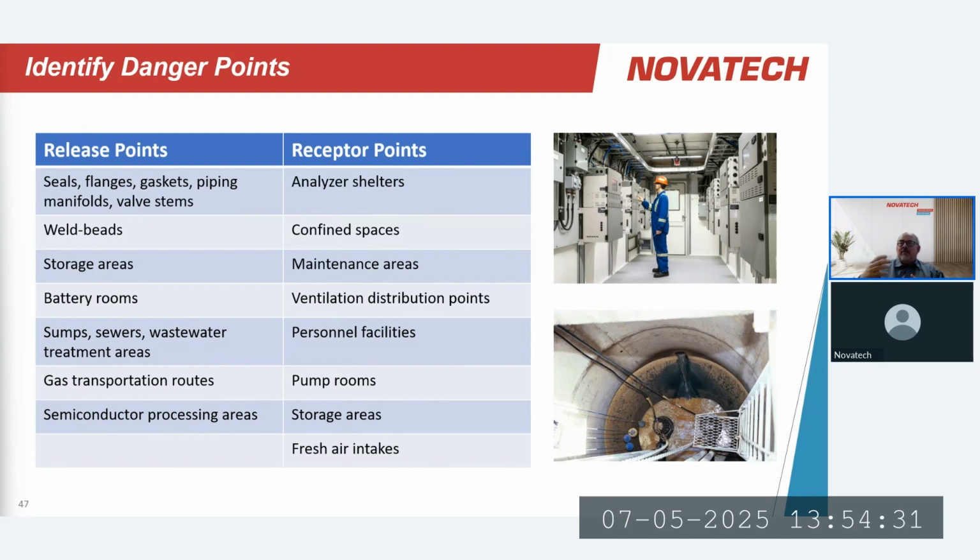We may look at, from a different perspective, rather than looking at the points of release, we may look at the points where we are concerned about the gases being present, whether it's where personnel may exist, so something like an analyzer shelter, a maintenance area, a walkway.